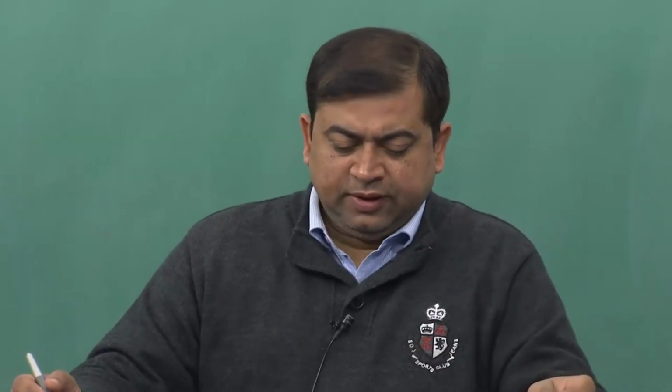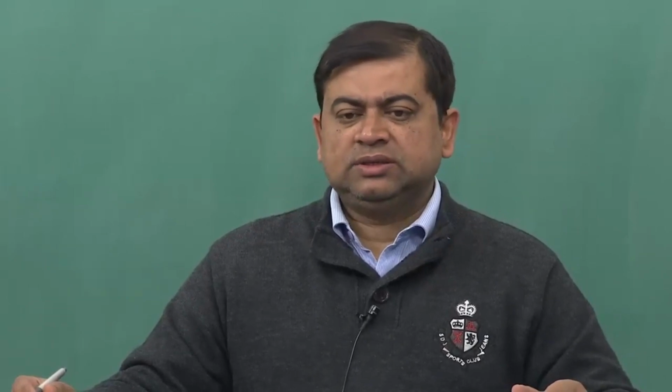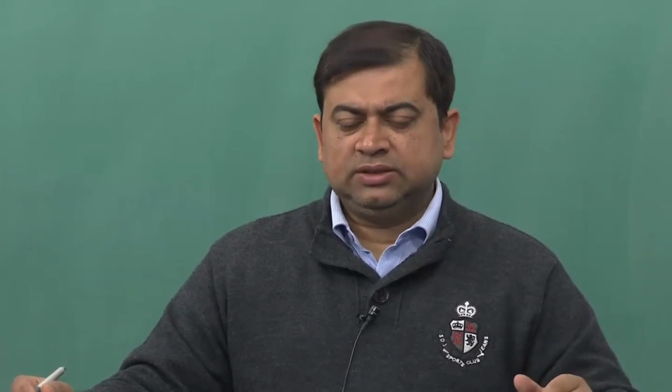Hello and welcome to this manufacturing process technology part 1 module 8. We were talking about how dislocations help in changing the overall ultimate yield stresses of a material, and what was deciphered was that because of the presence of the dislocation, the shear modulus of rigidity gets changed by almost 100 folds, meaning thereby that the ultimate yield strength goes down in shear by about 100 folds.